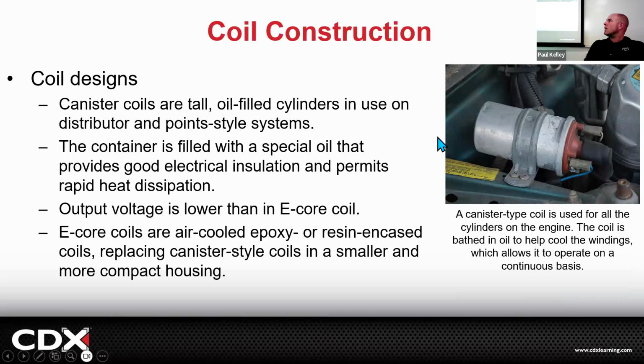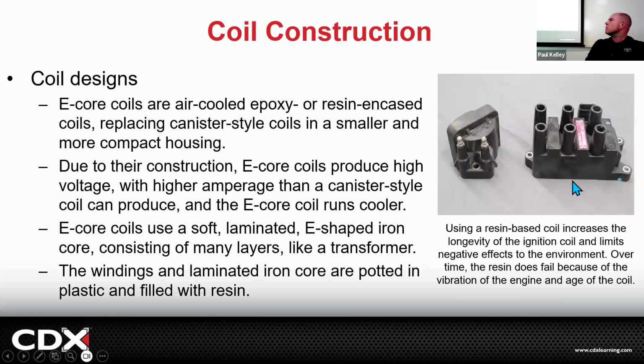I'm not buying it then. Right? So we didn't go from 1 to 8. We went from 1 to maybe still 1, but a bunch of coils in a pack, or maybe this one does 2 cylinders at once. So you could get away with just 4 of these rather than 8 of them, right? But it's been a progression. And now you're at 1 coil per cylinder. And there's a lot of benefits to that, but it does drive the price up. And that's just the way that things are going. Drives the price up, but it's more efficient. It's going to be easier for the ECM to control precisely. It's going to be a little better for emissions and fuel economy, right? Like the same things it always is, right?